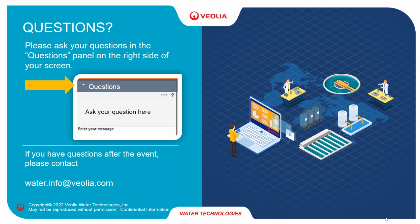Okay. Another interesting question has to do with nitrification. Has there been any analysis related to N2O emissions that can result in nitrification systems? There were some studies done a few years ago, and I know the techniques used for measuring N2O have evolved tremendously in the last few years. So new studies would be required to have much more precise numbers on N2O emissions. The first preliminary numbers we could measure a few years ago were that these emissions were somehow similar to an activated sludge system. But we could see some spikes in N2O generation being emitted right after backwash.